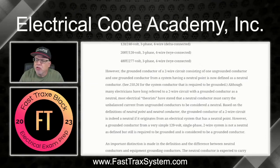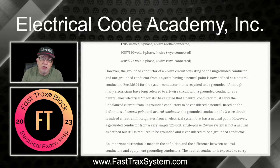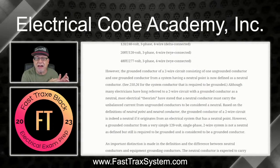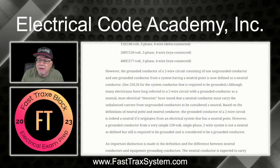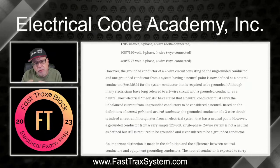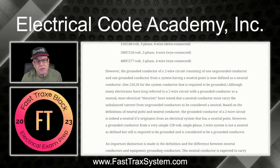The black. So the purists say, well, it cannot be a neutral, but it is a grounded conductor, because as you'll see in an illustration here in a minute, it is connected to a grounded system. So it is a grounded conductor. But the theorists, the purists, will say, yeah, but it's not really a neutral because of the definition of neutral, at least to the point where the code panel had to get neutral conductor into the code, okay?